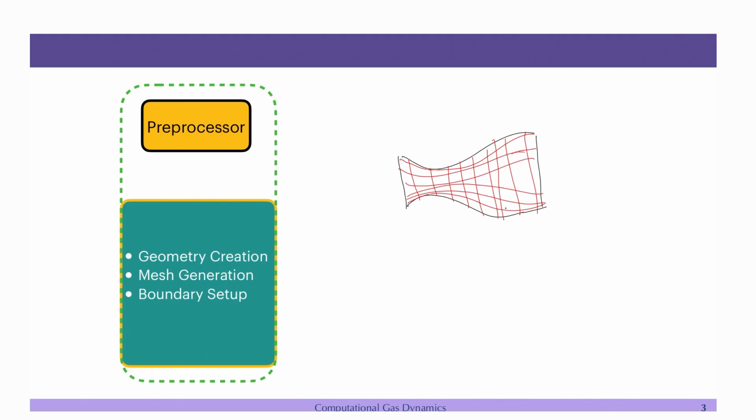What you see in red are the boundaries. Here you have to apply the boundary conditions, on the left, on the right, and so on. You might have the total pressure here, and maybe the back pressure there, depending on whether it is an over-expanded or under-expanded nozzle, so you have to adjust the back pressure accordingly. This might be the wall, on both sides. It may be a 3-dimensional configuration, or you may think of making an axisymmetric configuration, then you have to apply an axisymmetry boundary here, or you can simulate a wedge kind of configuration. So, this is an example of internal flow.